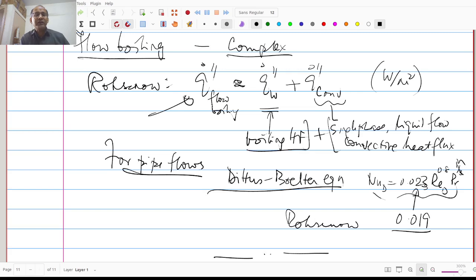And in order to complete the understanding and discussion of all the analytical methods that we have available, we also looked at modeling of turbulence using different classes of turbulence simulation: direct numerical simulation. We talked about LES and we talked about RANS, the Reynolds averaged Navier-Stokes equations. And in RANS, we looked at the Reynolds stress models, where you solve separate differential equations for separate components of stress.